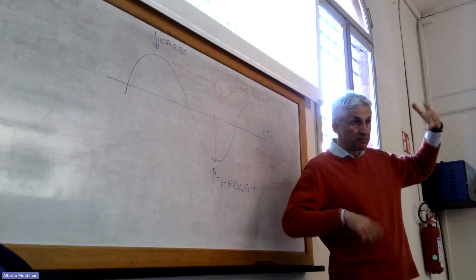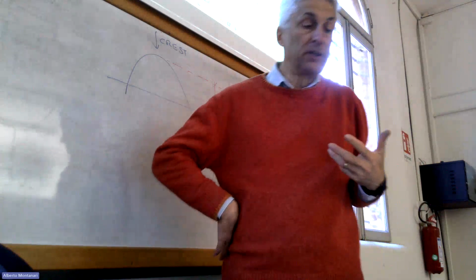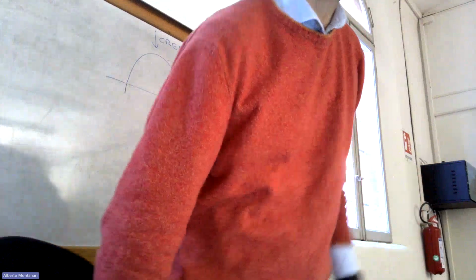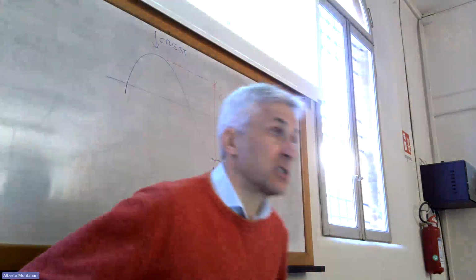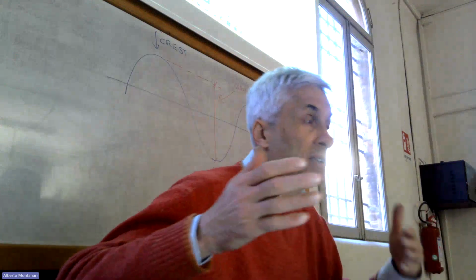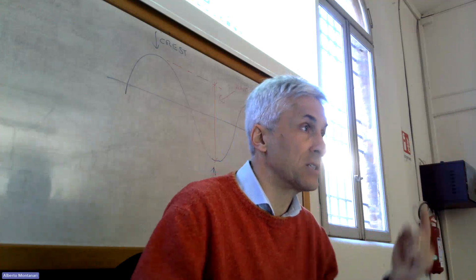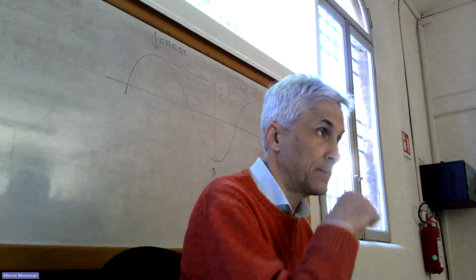It's quite obvious. You can understand that if the return period is 30 years, at least we would like to get 30 years of observations in order to get an understanding of the wave height that may occur once in 30 years. Okay.